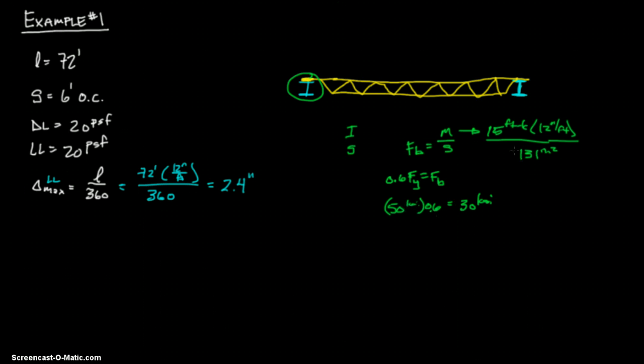And you find out that the actual bending is 1.37 KSI, and that is much, sorry, wrong way. You'll find that it's much, much less than 1.37, and therefore you're good to go. So this is your allowable stress, and this is your actual. I guess I could write that real quick.